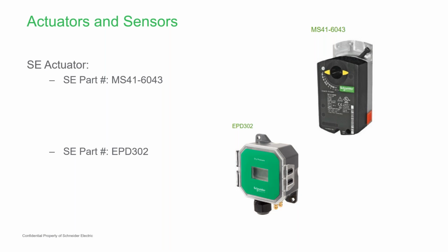Again, the damper actuator is 0 to 10 or 2 to 10. We can have others, but to have some other 0 to 10 volt signal range, you would have to write a little Lua script to rescale that. But by default, we can handle 0 to 10 and 2 to 10, which is very common, not 4 to 20 milliamp, 0 to 10.